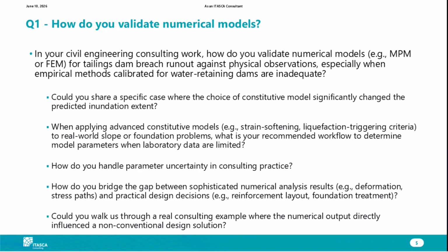We need to shift, I would say, our mindset toward performance analysis and not just factor of safety per se. Factor of safety per se is very limited. It doesn't tell the story. Most of the time, you get into litigation not because the factor of safety was 1.27, but because the embankment moved several inches and the structure went out of service. What was the factor of safety in this case? Nobody knows, but the performance is visible.